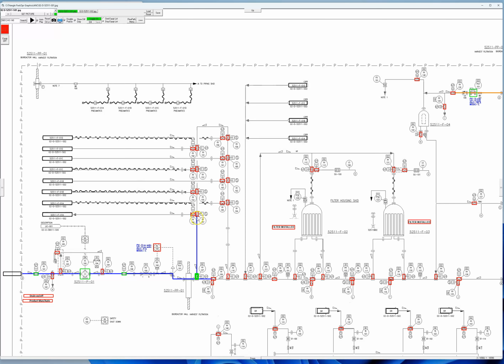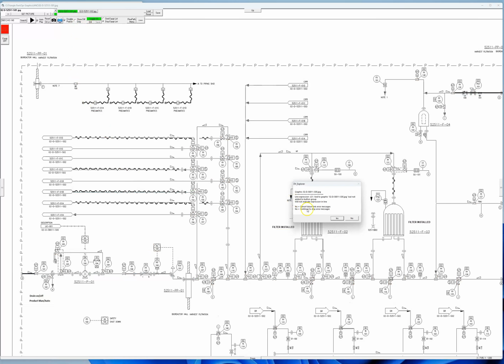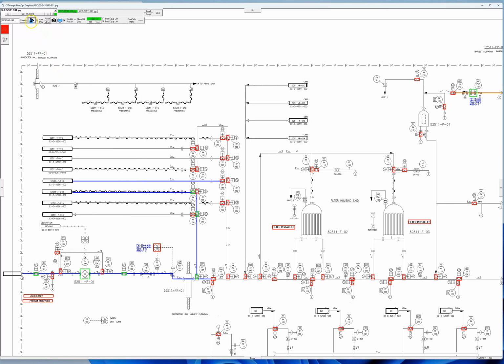So it goes up here, up here. This is in to the pod. Let me open this up. Now, as you can see, this line automatically opens up. How does it do that? Or how does it know? Basically, it looks at the other P&ID. Depending on how that's set up, it will update this drawing accordingly.